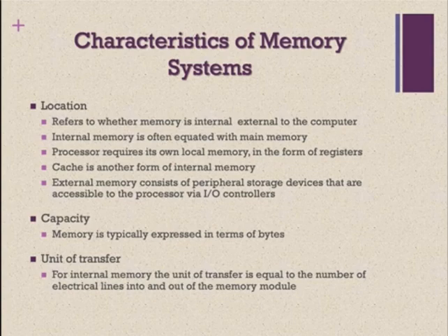One cycle may be 1 nanosecond, or less than a nanosecond, but 1,000 cycles is a lot of time in the context of a processor. So the processor needs memory that it can access within one cycle, because the processor executes an instruction in one cycle or two cycles or a few cycles, depending on the instruction. Execution is just a few cycles.